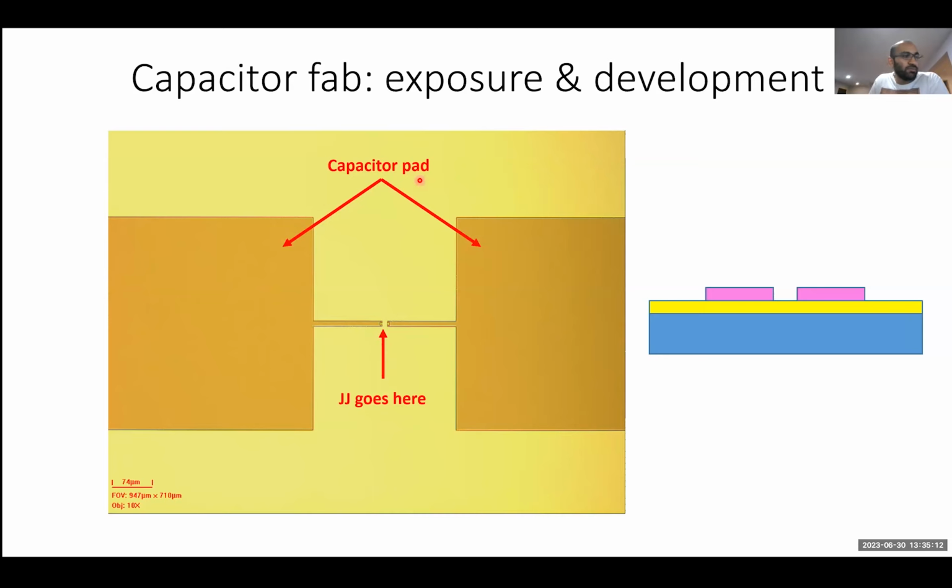And in order to improve the chemical stability and the chemical resistance of that resist, you can hard bake the resist. And a true hard bake is something that's done at much higher temperatures, like above 150 degrees, where the polymers in the resist will actually cross-link with each other and essentially strengthen those interactions, making it very hard for that resist to degrade.